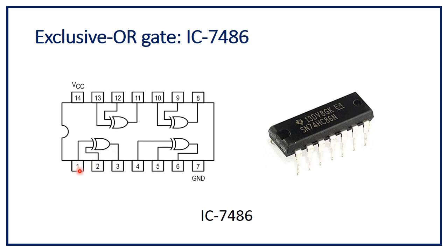Here pin number 1 and 2 are inputs and 3 is output. 4, 5 are inputs and 6 is output. Here 13 and 12 are input pins of XOR and 11 is output. Here 10 and 9 are inputs and 8 is output.